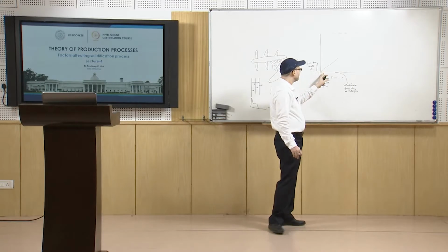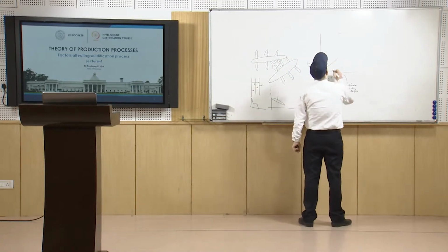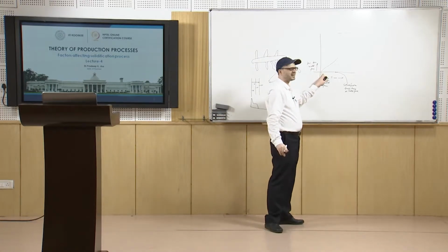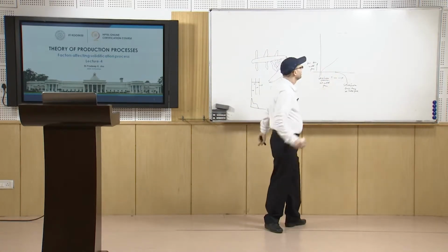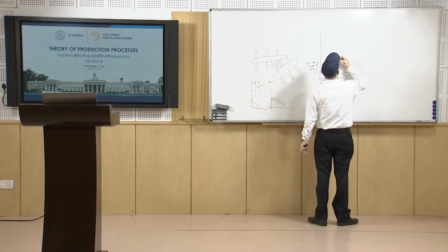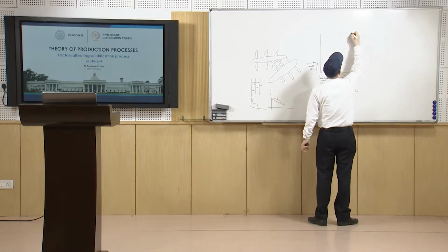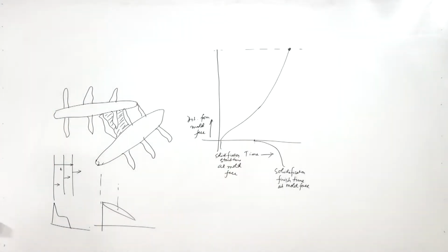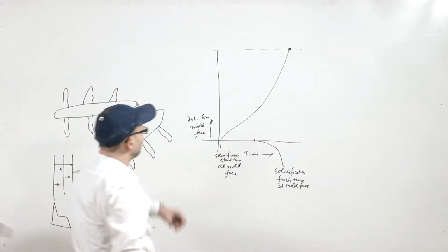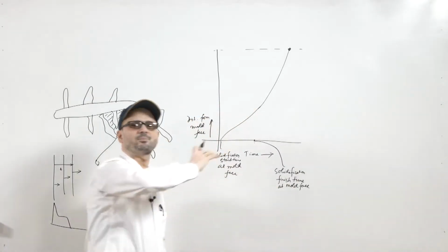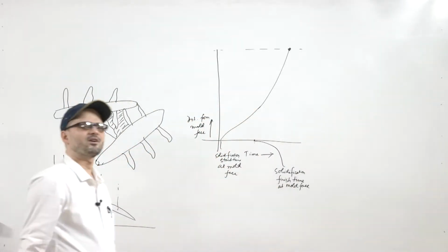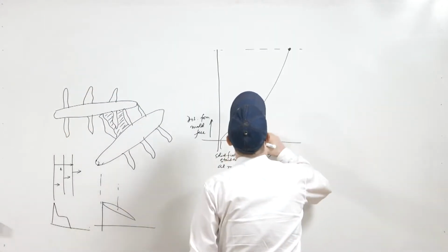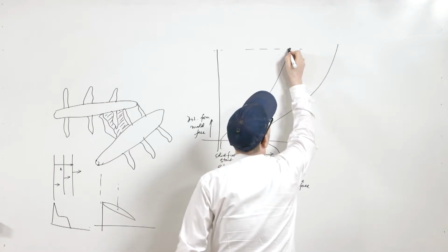It was seen that at the mold face solidification starts here and finishes here, whereas at the center line the solidification was over at this point. When the temperatures at different points are recorded, and it is seen when the solidification gets completed, the solidification complete line goes like this.